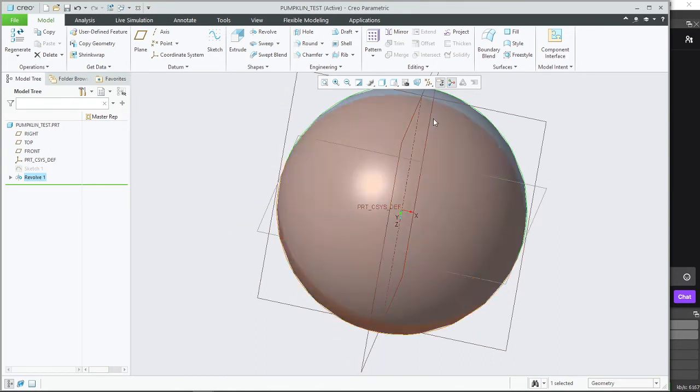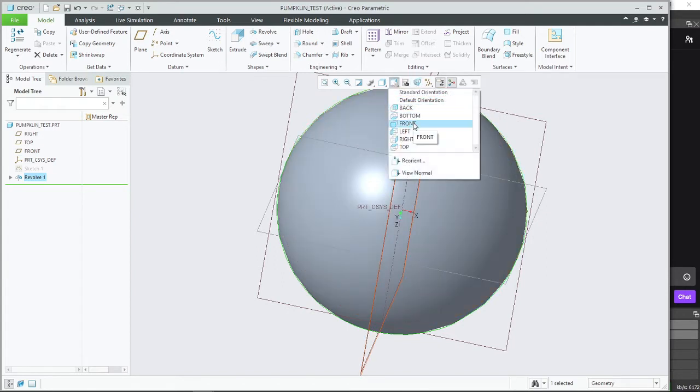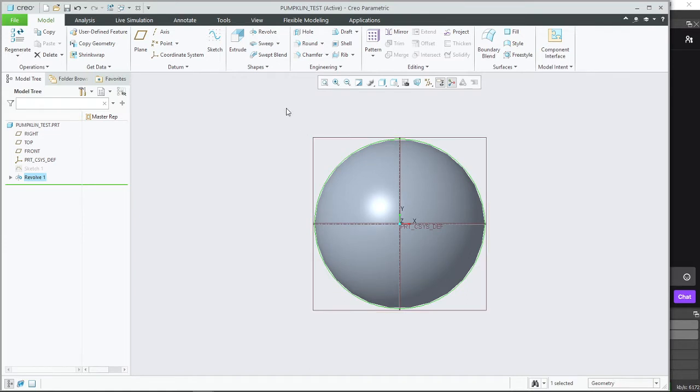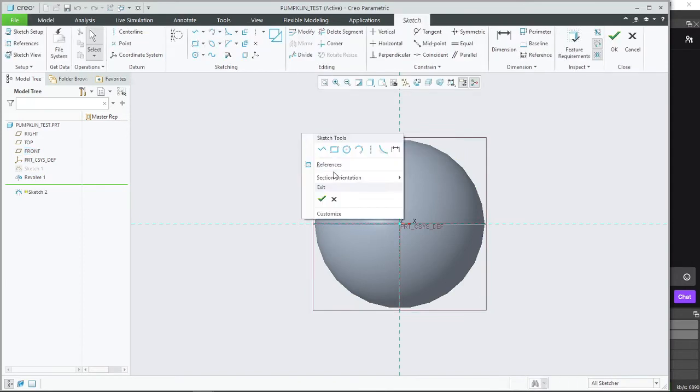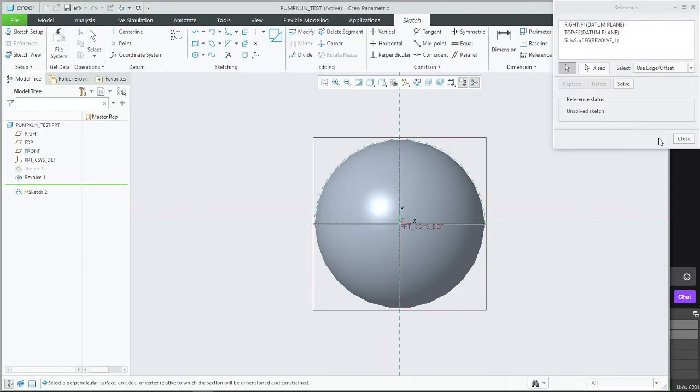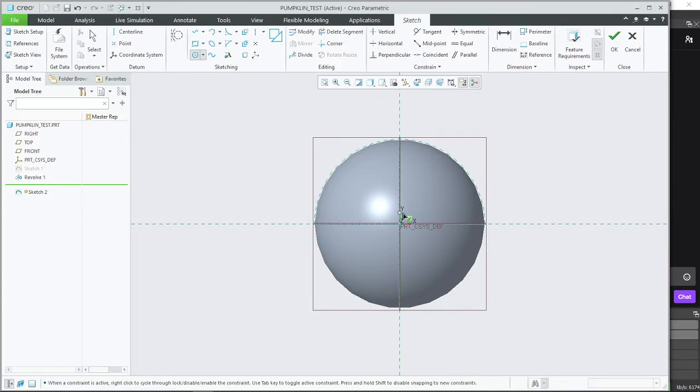Here, I would need to actually draw a line on which I would have to say, please start curving in this line, and that would be by selecting the front, then saying, please let's create another sketch on this plane using the surfaces of the ball as a reference. I would again make another curve which is the same size as the ball.